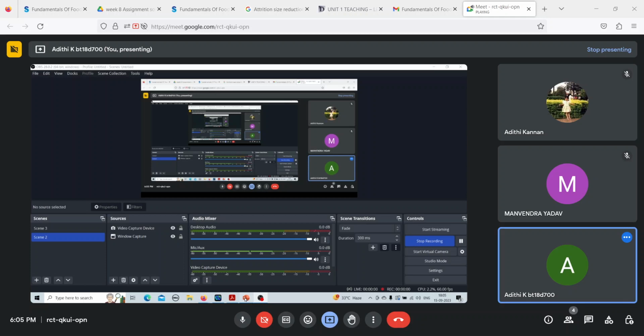And for the pan, since the stage is 0, this is 0 into 12 by 110, which is also equal to 0. So now you add all these values. This is the summation of fraction of weight into sieve stage. So you add 0.36 plus 0.49 plus 0.65 plus 0.30 plus 0, which gives you the value of 1.81. So your fineness modulus is equal to 1.81. This is how you calculate the fineness modulus. A similar problem has also been discussed in the video lectures as well.